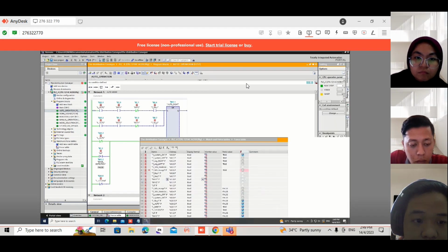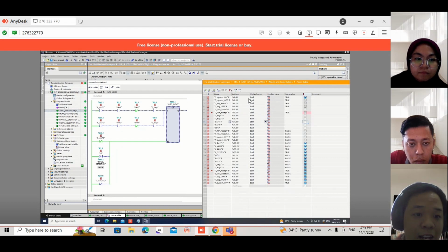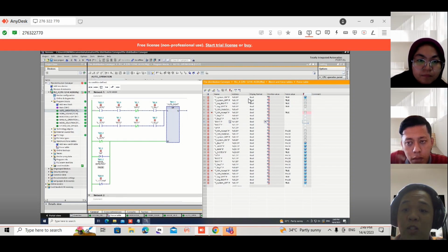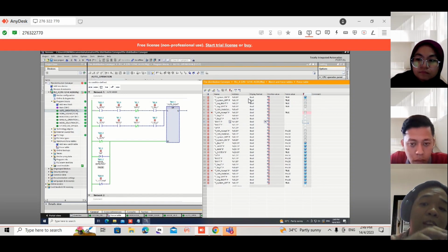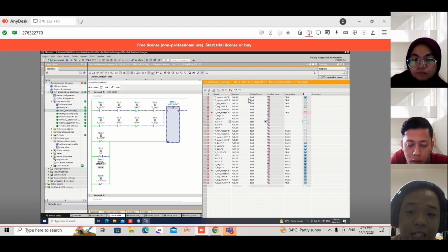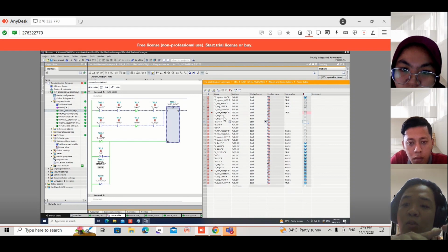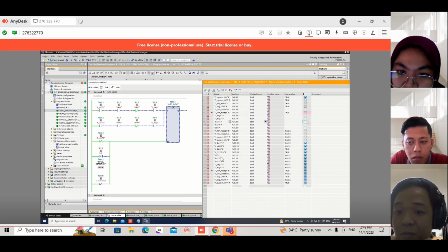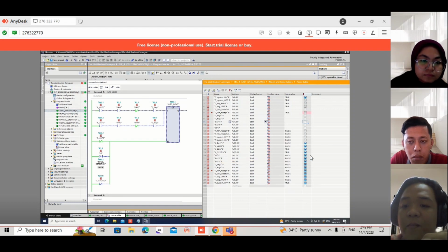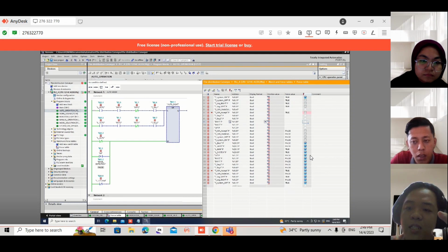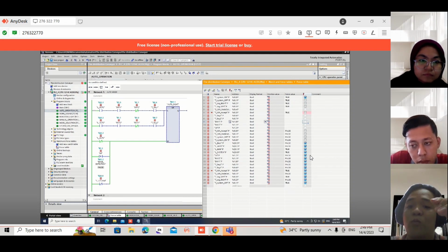The conveyor belt will keep moving to the right until the part reaches the final check, which is like the finish line, or until someone switches off the auto mode. So in simple words, when there's a part in bay 1 and bay 2 is empty, and someone presses the bay 1 button, or when there's a part in bay 2 and bay 1 is empty and someone presses the bay 2 button, the conveyor belt will start moving the part to the final check automatically. It will stop when the part reaches the final check or when someone turns off the auto mode.